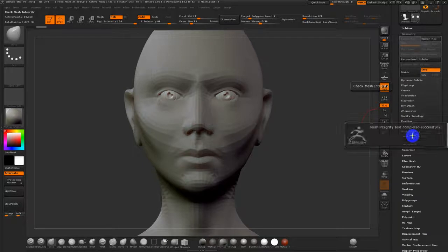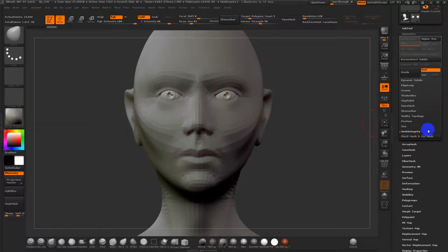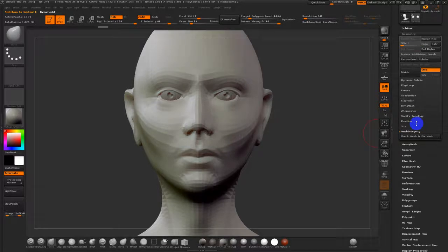I'll go to Check Mesh, and then I'll say Fix Mesh. Just, again, out of paranoia, I don't want things to bug out on me, especially at this stage. When you're nearing production quality, you don't want things to blow up on you. So what can happen, particularly with mesh that you need for blend shapes. Blend shapes are very sensitive to the vertex naming and ordering or numbering, as well as the mesh layout. So if there's any little bugs and you fix those bugs, the problem is you may destroy your blend shapes afterwards, which means you have to redo all the blend shapes. So you want to try to clean the mesh and make sure it is as production ready as possible.